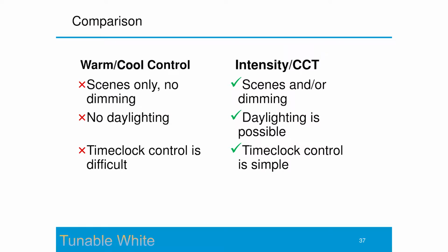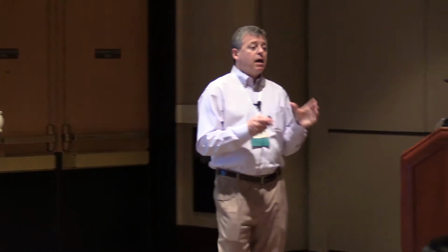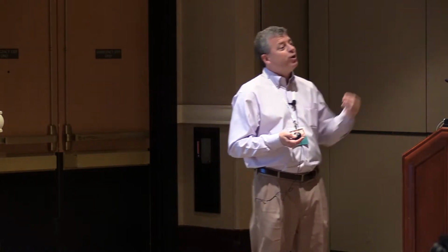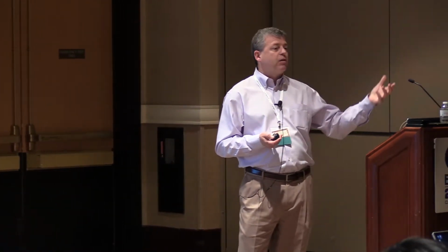So the comparison between those two we've already talked about. I think the other element of a lot of these codes is that most codes that we've dealt with in lighting control systems in the past were as simple as occupancy sensors initially, and then occupancy sensors and time clocks, and now daylighting. It's important to know that any consistent system out there today has to take into account whatever codes may be. So in the state of California, the codes are going to be more strict on energy than pretty much every other state that we deal with.